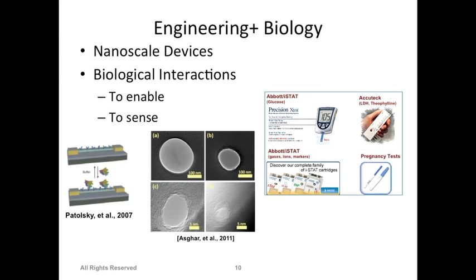And because of the wetting property, if you put a solution, and that's the case here, when you take a urine sample and put it there, it automatically goes to the other side. You don't really have to push it. So it's a passive flow. You don't have to use syringe pumps or other methods to push a liquid from one place to another place. That's a very big benefit we get when we make cellulose paper based devices, because then you can make those devices for point of care applications, or maybe at home diagnostics. You can develop that with paper.